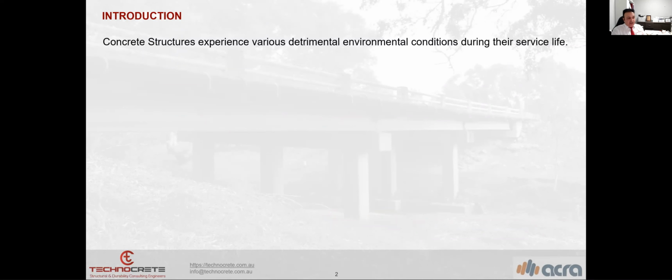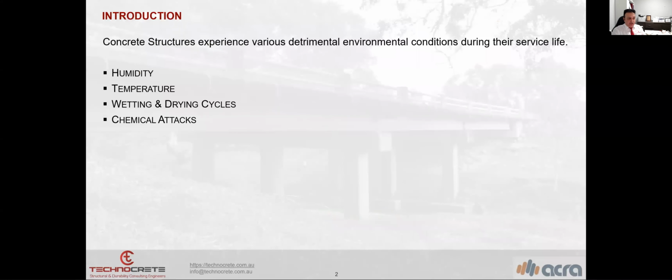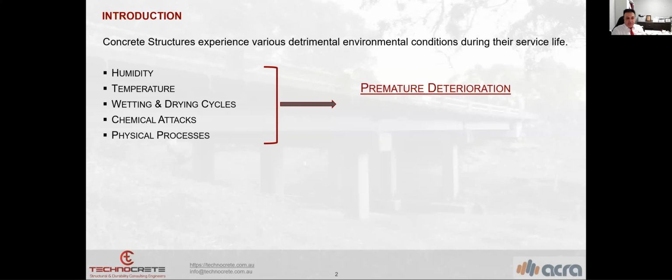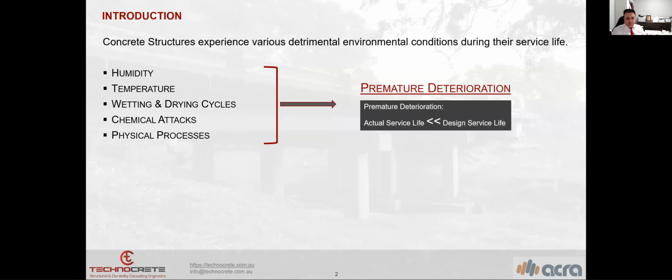We know that concrete structures and infrastructures experience various detrimental environmental conditions during their service life, like high humidity, temperature, wetting and drying cycles, chemical attacks, and physical processes. All of these will result in premature deterioration of the concrete structure. What does it mean? It means that the actual service life of the structure is less than the design service life.